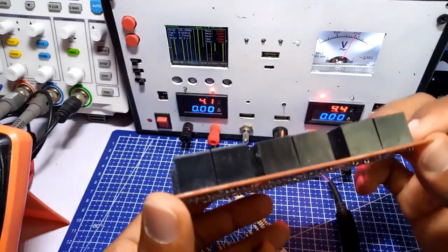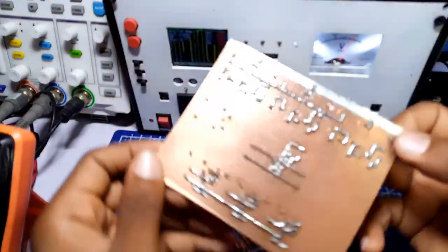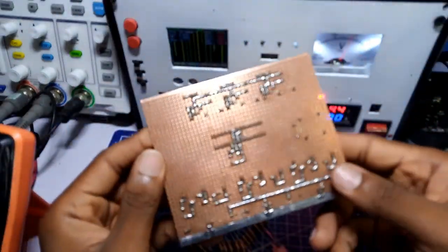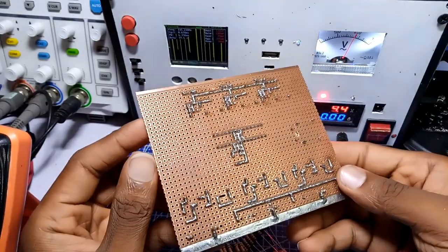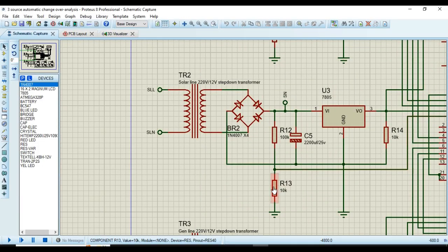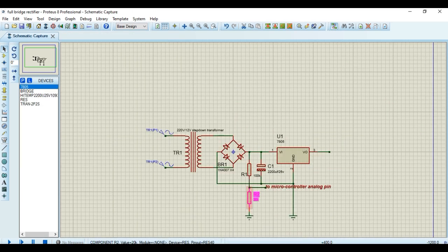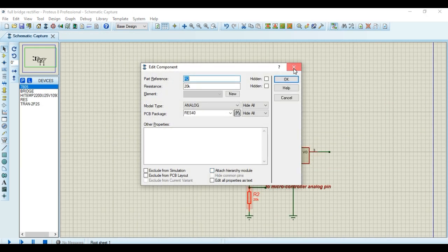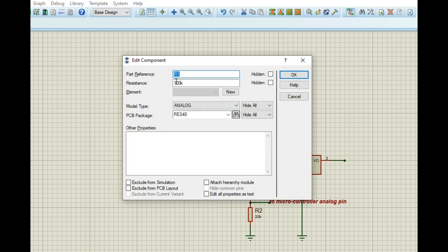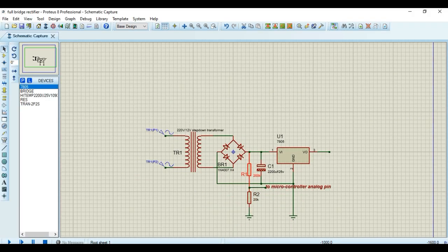This voltage divider network is the same in all of the sources circuit, and I use it to read the relative AC voltage. You can use any resistor value from 10k and above for this measurement, but ensure that the resistor connected to ground relative to the analog point is 1/10 of the other, just as I'm using 10k with respect to 100k. So let's say you are using a 20k resistor, it is obvious that you should use 200k respectively.